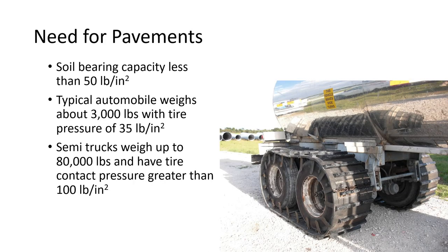So why do we need pavements? We need pavements because the pressure on the tires of vehicles is great enough that unimproved soil can't usually support it. Right. In some places, yeah, sure, you can. There are really hard soils in places, and you don't actually probably need a road, or at least not all the time. Sometimes it's seasonal. But in general, especially in the U.S.